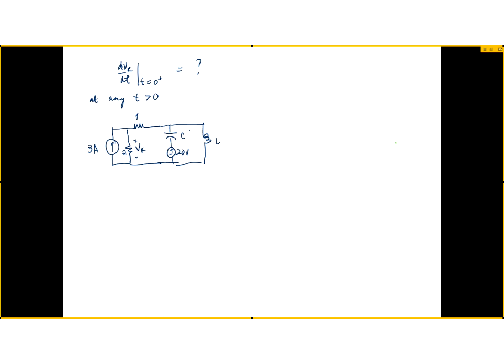So my hope is when I do the differentiation to find dVR/dt, the other derivatives that come out will involve things that I already know, or things that I can find. What are the derivatives that I already know I can find? dVC/dt, right, and dIL/dt.